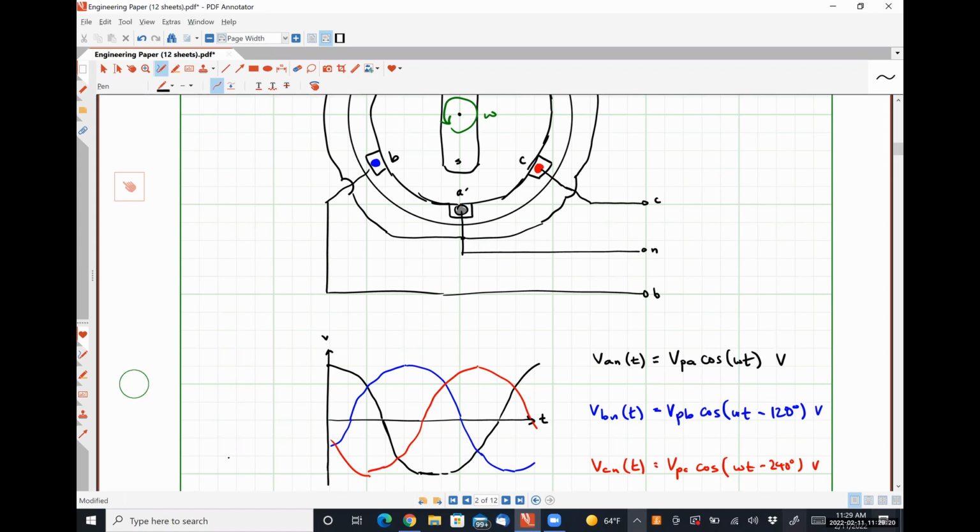You take your three-phase power and put it through a three-phase rectifier, which generates a DC signal. That DC signal is then chopped up by what's called an inverter that spits out square wave approximations of sinusoids at different frequencies that allows you to actually change the speed of the motor.